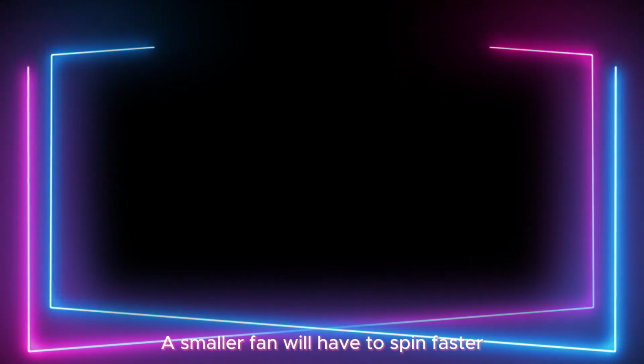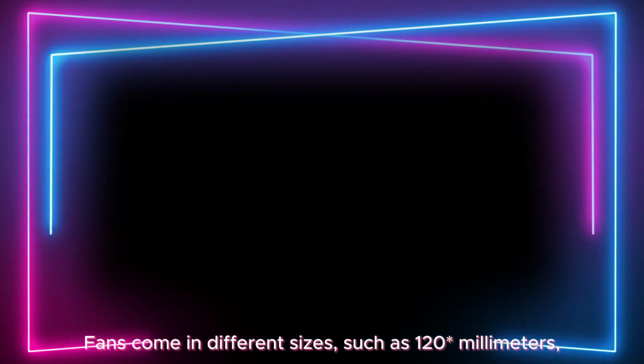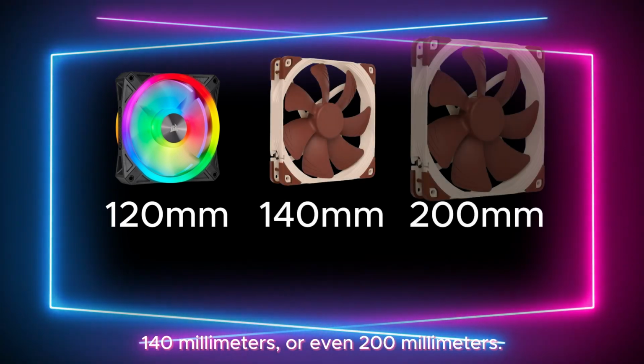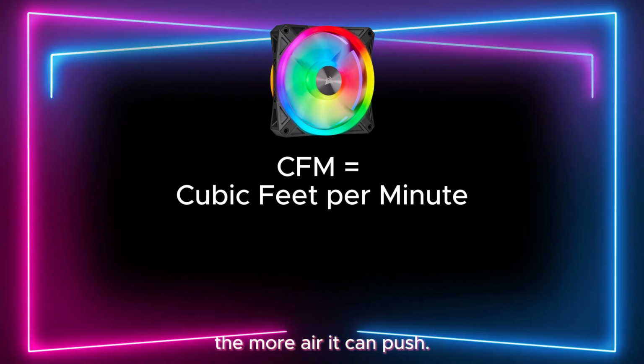A smaller fan will have to spin faster to push as much air as a big fan, which will result in more noise. Fans come in different sizes, such as 100mm, 140mm, or even 200mm, but most PC cases only support up to a certain size. Every fan has a CFM, and the higher it is, the more air it can push.